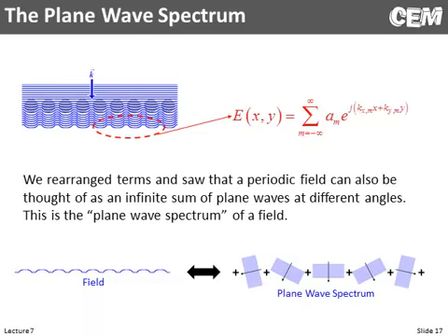And what it turned out is the thing that they were measuring diffracted, but this FTIR instrument was only able to record the zero order mode, the thing that went straight through. So in their model, they were accounting for energy everywhere. In my model, I ignored that because that's what the spectrometer was doing, was ignoring that, and it was a virtual overlay. So that's where the art of modeling comes in. But if my codes didn't have the ability to decompose fields into the plane wave spectrum, I wouldn't have had the ability to do that. And I suspect that's maybe one of the reasons that they didn't realize that, because they weren't decomposing their field into these spatial harmonics. So there is definitely utility to it.